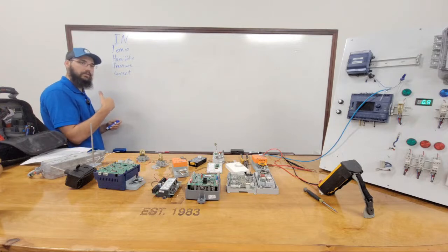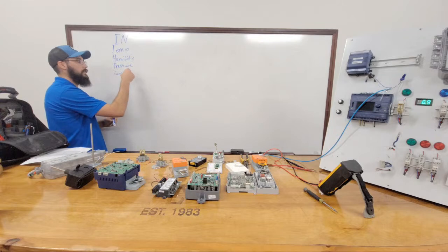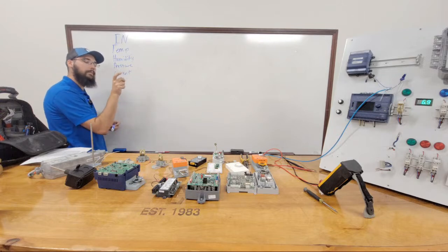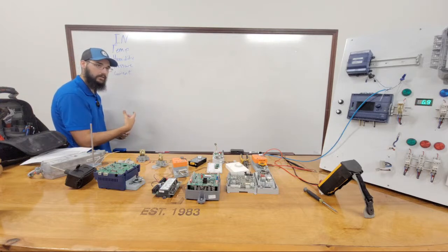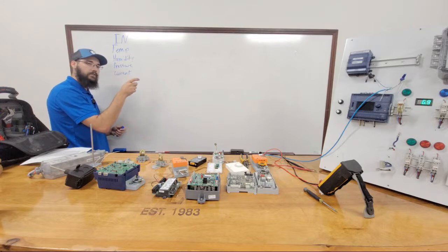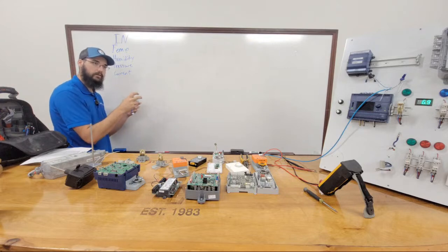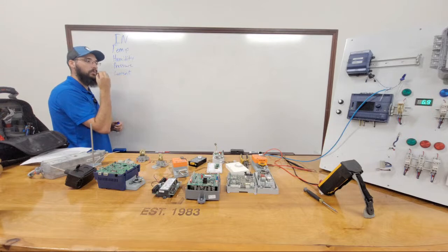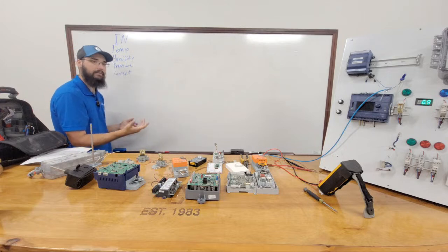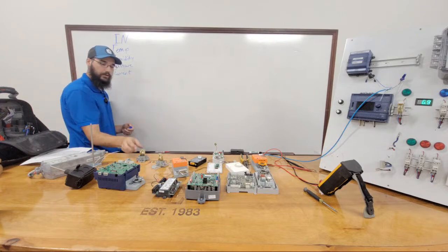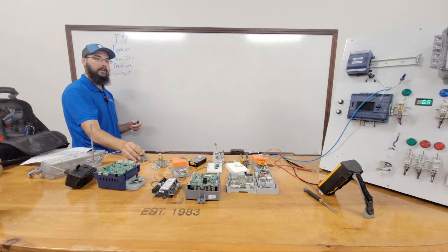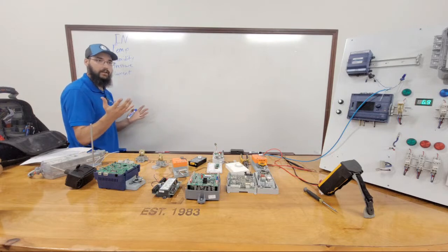So if you had a current relay, then the clamp would clamp around, say, the common leg or L1 of whatever motor you're trying to get a status on. The magnetic field off of that motor would be what activates that relay's coil, if you will. Most of the time a current relay is set to activate at like 1/2 amp or a full amp, depending on the size and style. And then all we're doing is closing a set of contacts inside that relay, and it's activated.